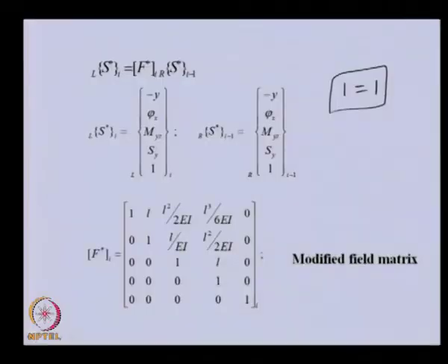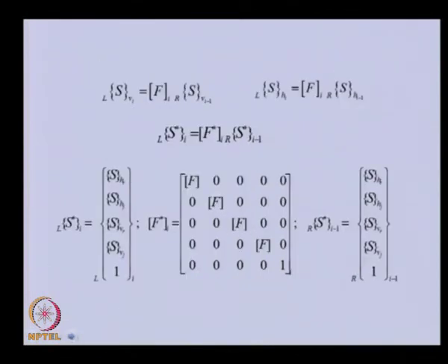So, for that case, when we are considering both plane motions and when we want to consider the damping or gyroscopic aspect also, then we need to do the following. Here you can see this is the state vector which is in the horizontal plane, these two are in the horizontal plane, these two are in the vertical plane. In the horizontal plane itself we have taken the real component and the imaginary component.